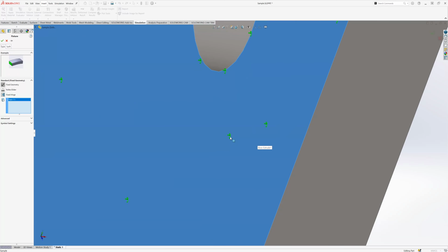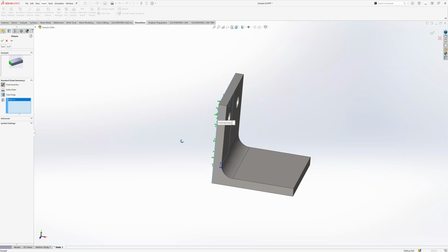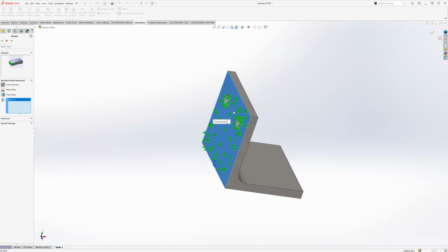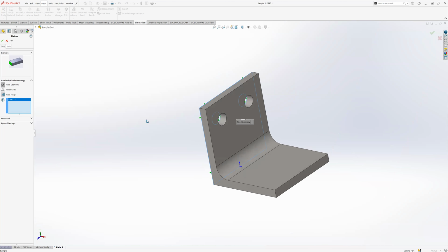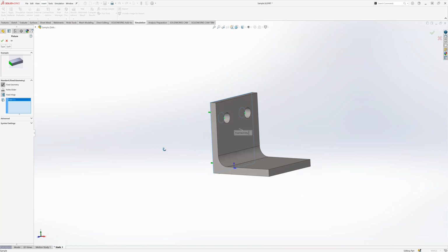You can see that not only do you have arrows in all three directions, you also have these little circular pieces. That means it's not only constraining displacements in all directions, it's also constraining moments in all directions. So this face cannot displace in X, Y, or Z, or rotate about X, Y, or Z. So pretty much when you do that, that'll fix that face. This is very similar to the example I did last time.